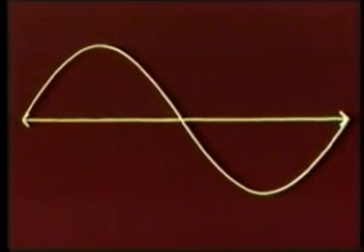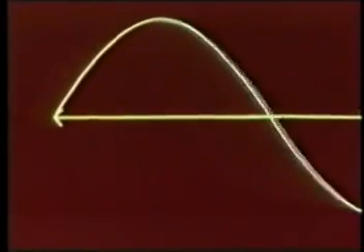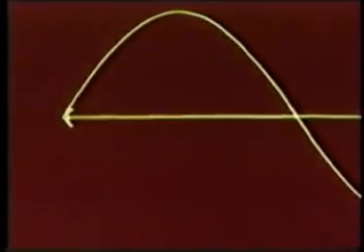We can relate the wavelength of the radiation to the antenna which produced it. An antenna which accommodates half a wavelength is the simple dipole. If we feed a signal to this antenna, an electron flow will be set up within it. The electron flow first produces a maximum concentration in this direction,